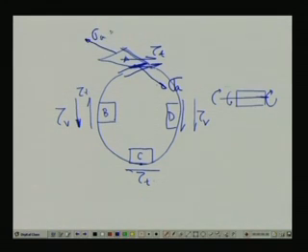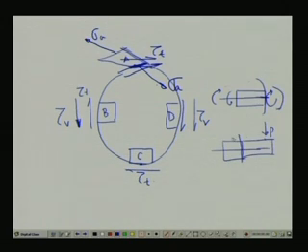And what about the bending? Now, if it is bending in this manner, what will be happening? If you look at the shaft, it is acted upon by load P somewhere here. We have taken the section here. So, this will be tensile and this will be compressive.